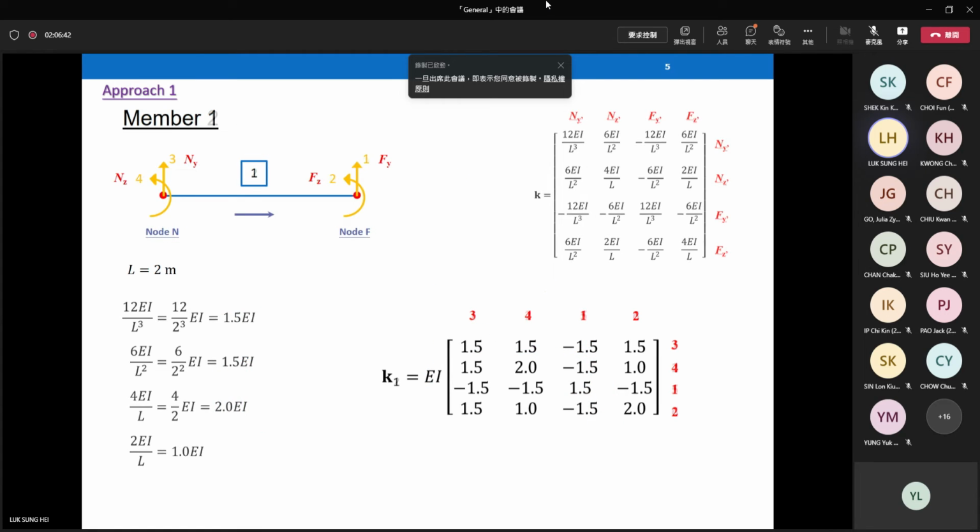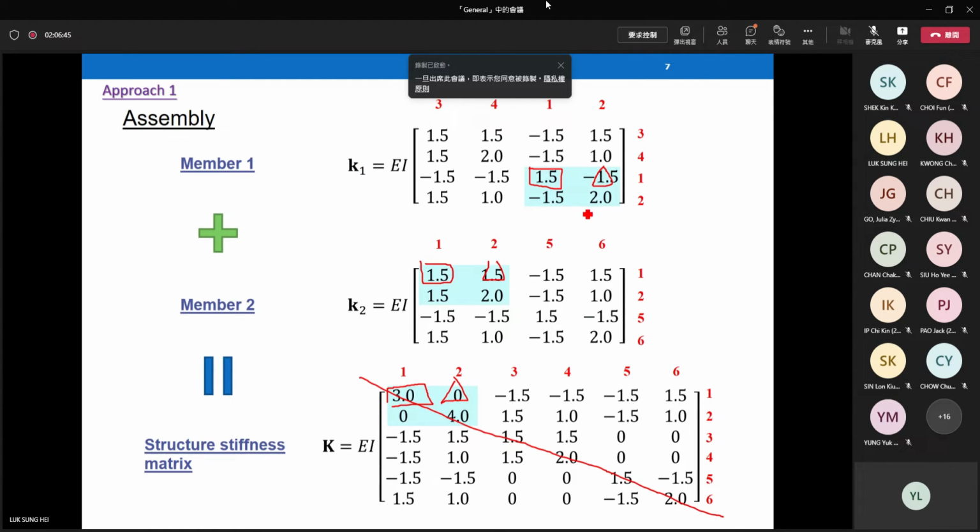Which part is K12, K22? You do a matrix partition. This is K11, this is K12, this is K22. These two parts are always multiplied by 0, dk, in this problem. So actually, columns 4, 5, 6 are not very useful. When you do the example, these two parts are actually useless. You may express them symbolically, like K12, K22. It will not affect your final answer. Just pay great attention to the first 3 columns.